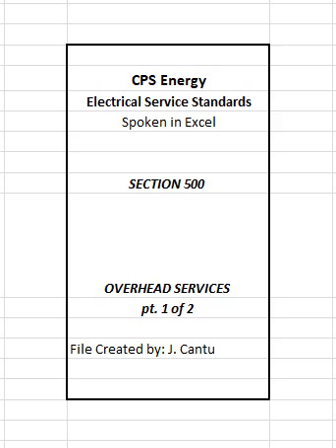2. On larger service drops, customer must furnish and install 5/8-inch galvanized all-thread machine bolts for installation in the building or structure during construction, especially for buildings of concrete, masonry, or brick construction. The machine bolts with galvanized washer and nut must be installed by the customer and protrude 2 inches outside the building wall. CPS Energy will install a clevis and insulator on these bolts when the service drop is installed.